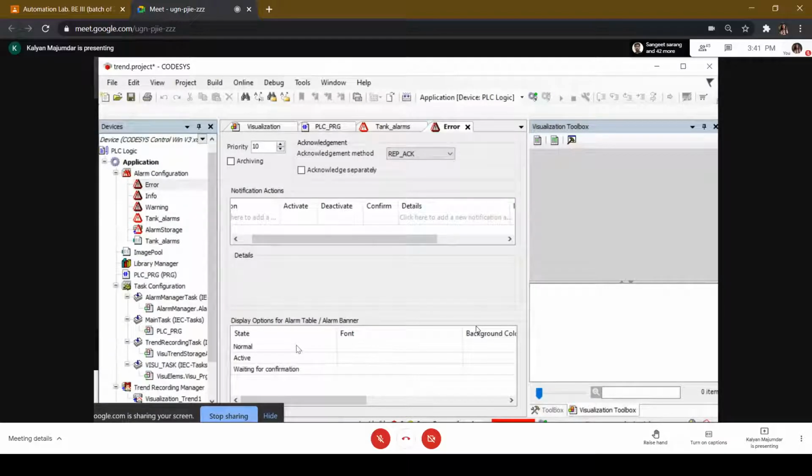So this lower table normally says the particular color codes corresponding to the alarm appearing, corresponding to the alarm being acknowledged, corresponding to the alarm getting back to normal. All those color codes are defined here. That's your choice. Plus the kind of text, I mean the font, whether it's bold and all that, is defined within this particular table. So that is what is alarm class. You basically define what kind of acknowledgement you're interested in and what kind of color code you're interested in to represent different states. They have already built in 3 classes.